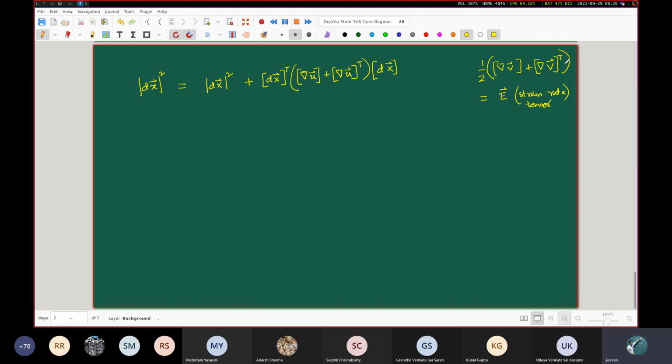Furthermore, you note what is this entire thing in terms of matrices that we have written, either this or this. So we define this thing, the strain tensor. Let me actually write this. The actual name for this is the infinitesimal strain tensor, or the small strain tensor. Because remember that we are working under the assumption from the previous slide that this only works if these derivative terms are very small. That is why we define the infinitesimal or small strain tensor. These two tilde symbols beneath the variable that I'm writing represent that this is a tensor of order 2. Just a way of writing it, and we define it like this.